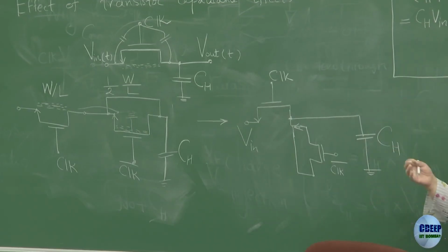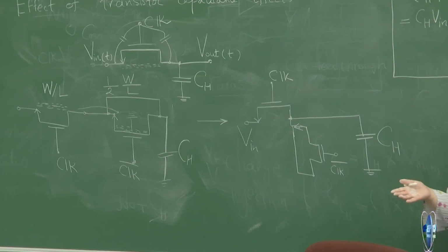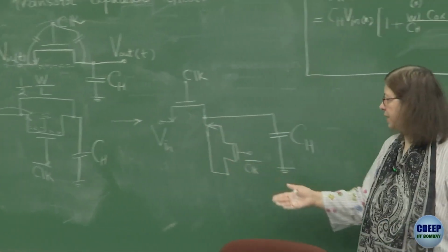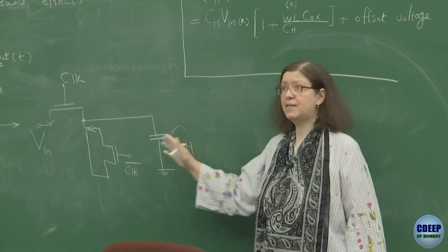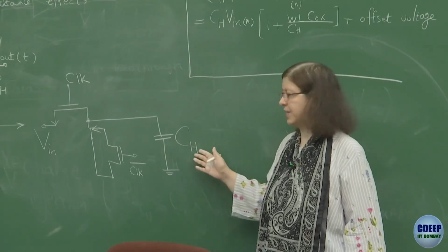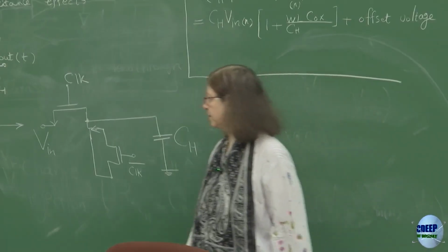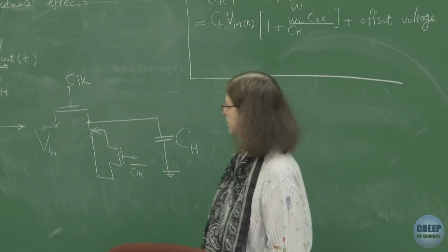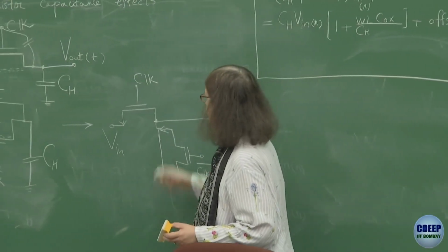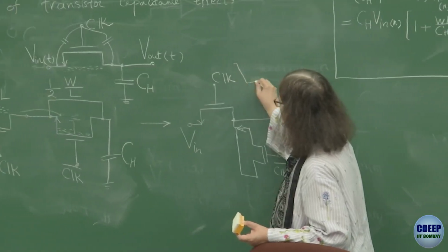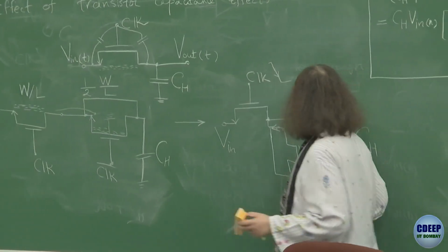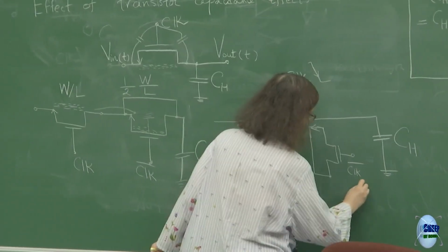At the end, it's like you are putting a dummy capacitor that also needs charge, right? So therefore, it will draw the charge from this channel, and less, we can't say 100%, but less charge actually will come over CH. Okay, and this is at the falling edge of the clock, which will be here, rising edge.